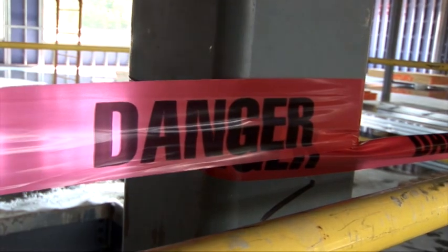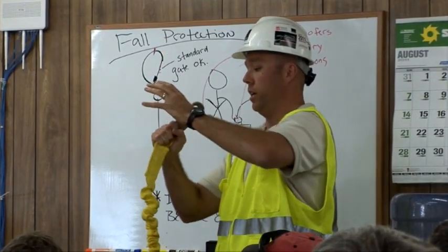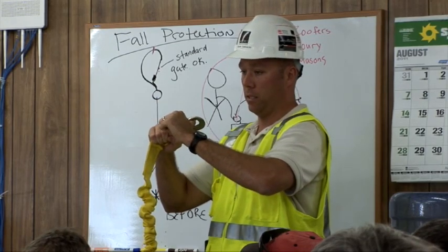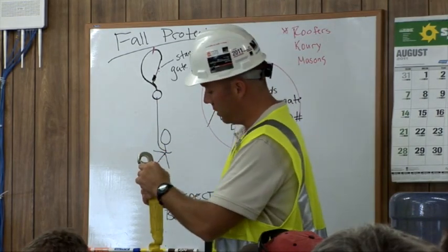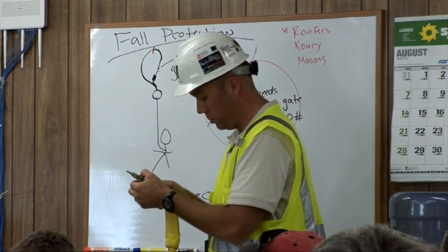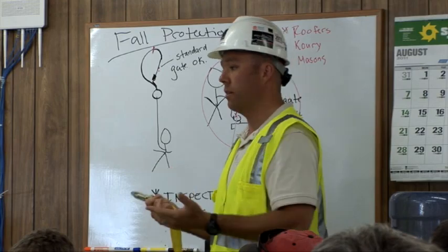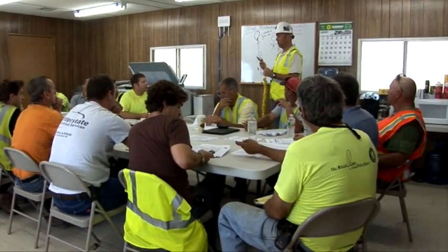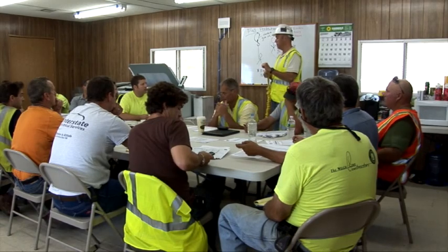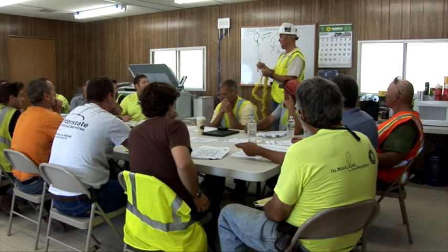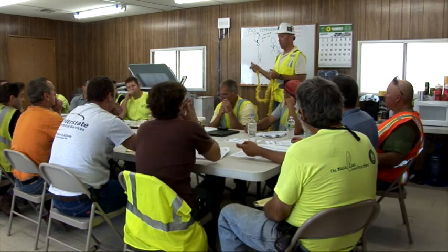The training must be performed by a competent and/or qualified person who knows the nature of fall hazards in the work area, the correct procedures for assembling, maintaining, disassembly, and inspection of the fall protection systems to be used, the use and operation of all fall protection devices, including fall restraint devices, arresting devices, and any other device that minimizes fall hazards.